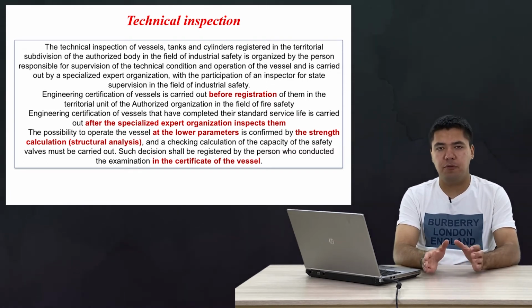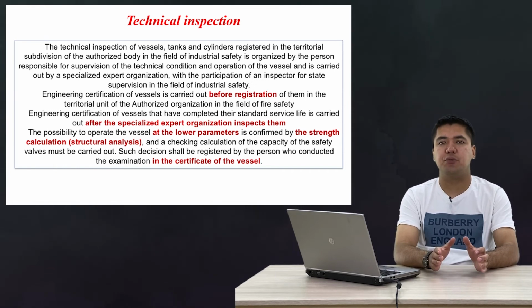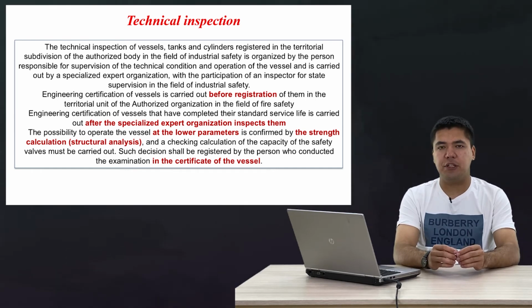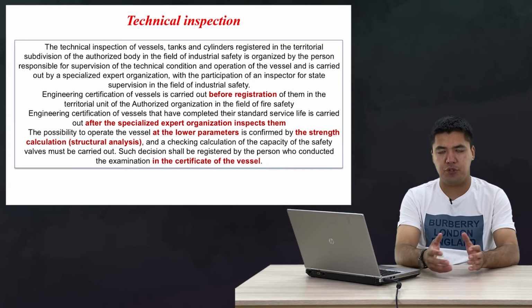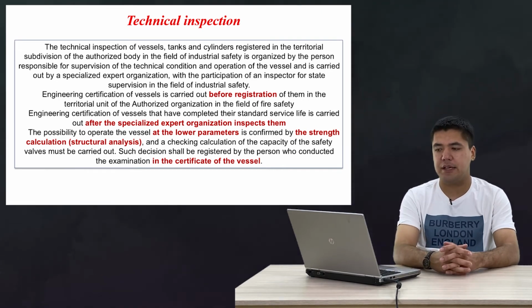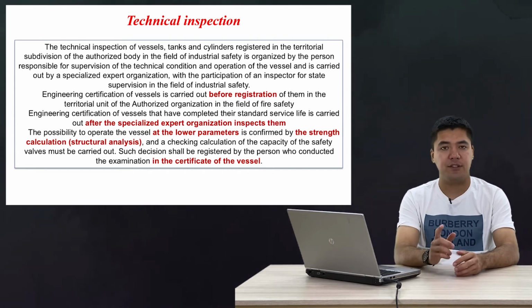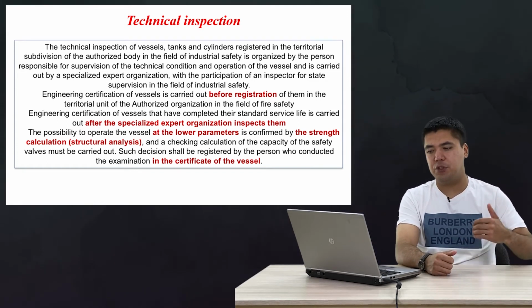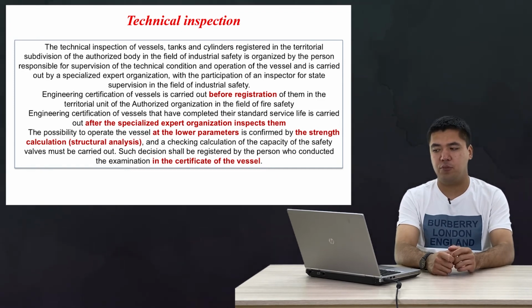And as I said, before registering all pressure vessels, they need to be technically inspected. And technical inspection will give permission to operate any pressure device in the following time. Also, engineering certification of vessels that have completed their standard service life is carried out after a specialized expert organization has inspected them. Then the possibility to operate the vessels at lower parameters is confirmed by strength calculation, and a checking calculation of the capacity of the safety valves must be carried out. Such decisions shall be registered by the person who conducted the examination in the certificate of the vessel.